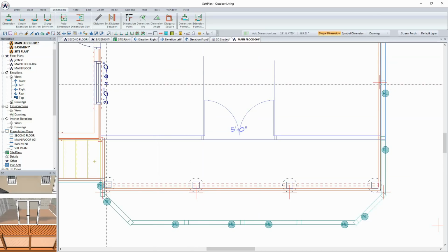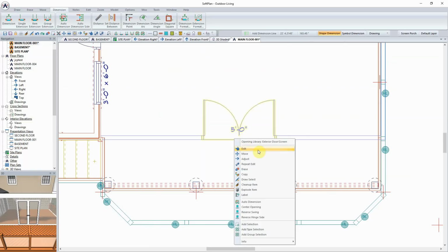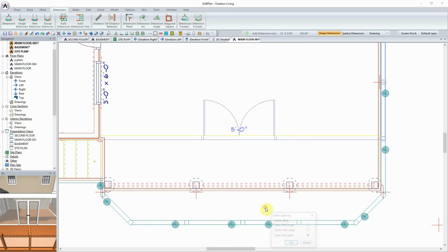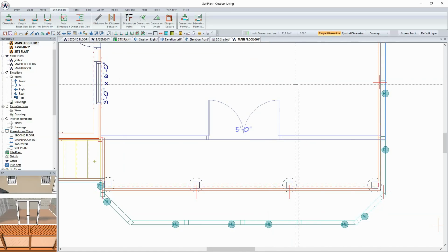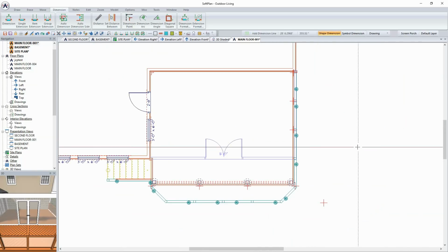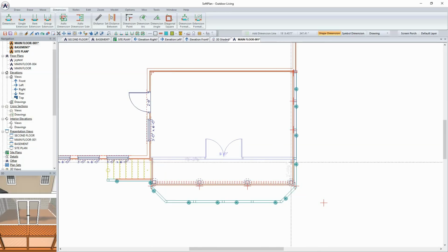These are currently running to the edge, as you can see, and I could run the cursor all the way through and then modify those dimensions to suit. I could also come in and just simply right click and center the opening so that I get it placed either along the inner wall length, the center of the wall, or the outer wall length, and then click OK and have the actual opening move for me. Okay, so that can all be done within just either editing dimensions or editing the actual opening, and depending on which dimension you want to center this on, you can set that up.